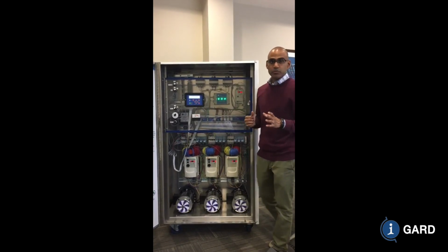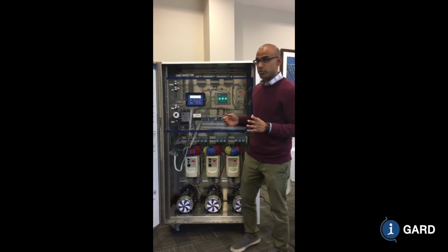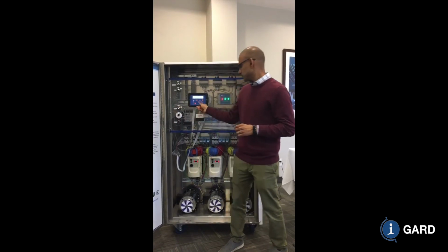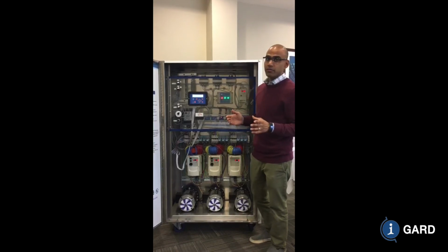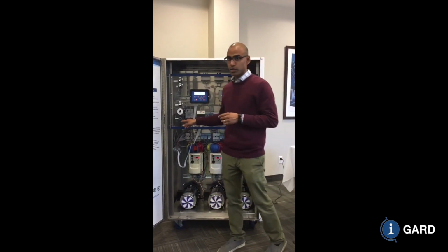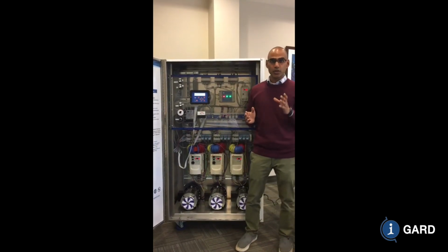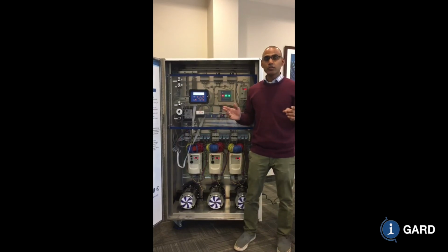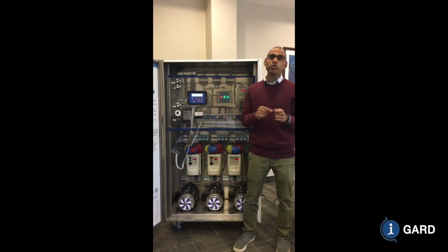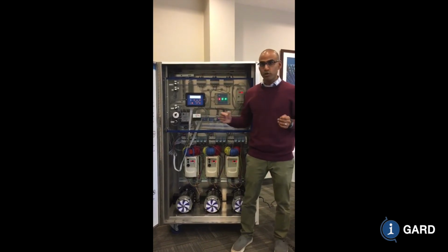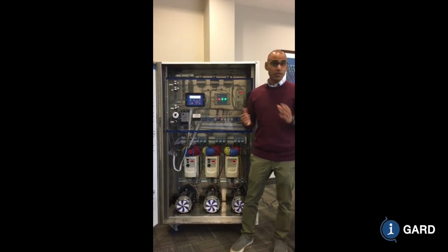Now let's have a look at creating a second fault and how the DSP behaves when a second fault is created. First I'm going to create a first fault. That's my fault on feeder 1, phase A. I'm going to create a fault on feeder 2, phase C, by pressing this button. Now that creates a double fault, because when you have a fault on two different phases, that can create a phase to ground to phase fault, which draws a large amount of current. It no longer goes through the resistor, so that's why it draws a large amount of current. That's a bad situation.